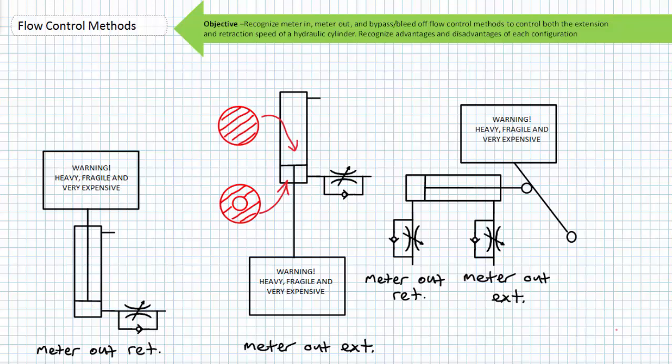Be aware certain meter-out configurations may result in pressure intensification beyond that of the system pressure relief valve due to area imbalances between the cap and rod end. For example, a suspended load hanging from a cylinder which lifts when retracted and lowers when extended. When extending to lower the object, both the input pressure supplied to the cap end and the lifted object are exerting pressure on the smaller rod end area. It's like an elephant and an elephant seal, both standing in the same donut-shaped area.